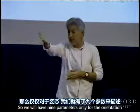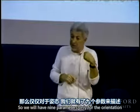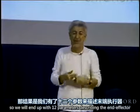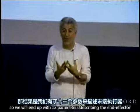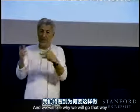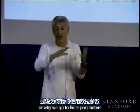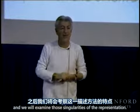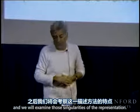So we will have 9 parameters only for the orientation, plus the position, 3 parameters, so we will end up with 12 parameters describing the end effector. And we will see why we will go that way, or why we go to Euler parameters, and we will examine those singularities of the representation.